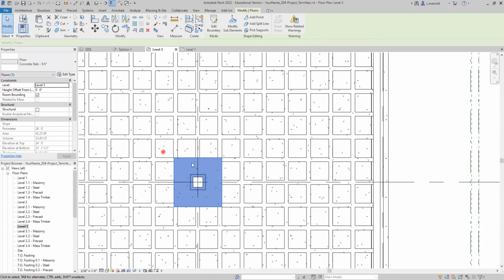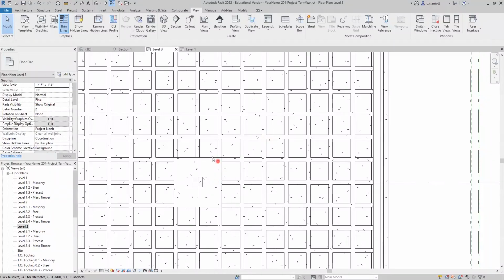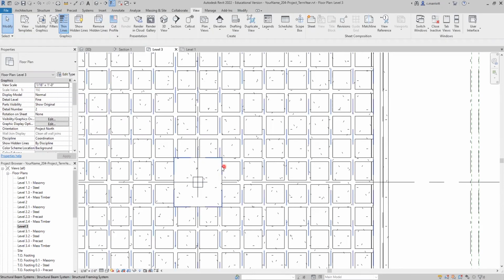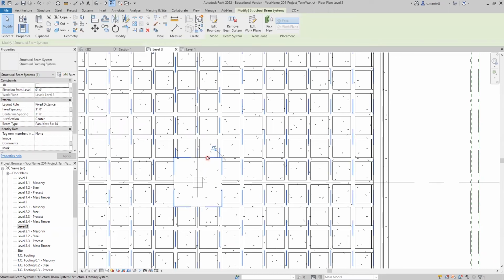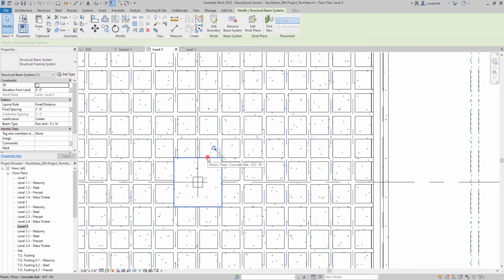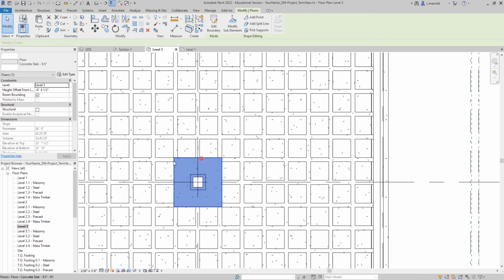One thing that you'll want to do is verify the height of this section of slab. So if you select it, you'll notice it's set to be at 0, and it actually is going to sit below the concrete slab that will go across the top of the whole waffle slab. So we want to drop that down -4.5. Okay, so now if I click on it again, and by the way, you'll find it useful as we get more things in the file, that if you hover over things and keep clicking tab, you'll eventually be able to select the object that you want. So I'm just checking, and -4.5 is where it should be.